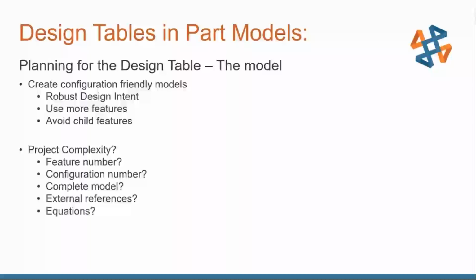And what about equations? That can definitely add to the project complexity. That can help with the automation. Maybe fewer parameters in the design table that you're controlling, more automatic updating within the SOLIDWORKS part model. Again, it can all work together. And of course, those equations can be Excel formulas and Excel equations. Very powerful tool. You can really do some programmatic functionality in your Excel file to really help drive the part.